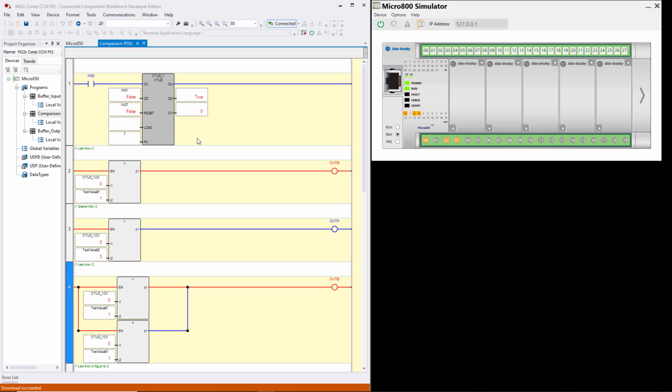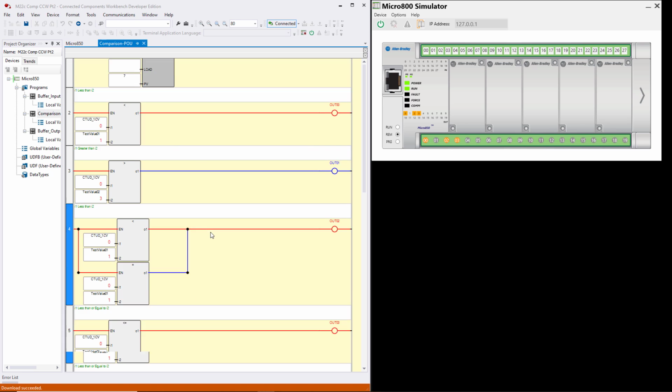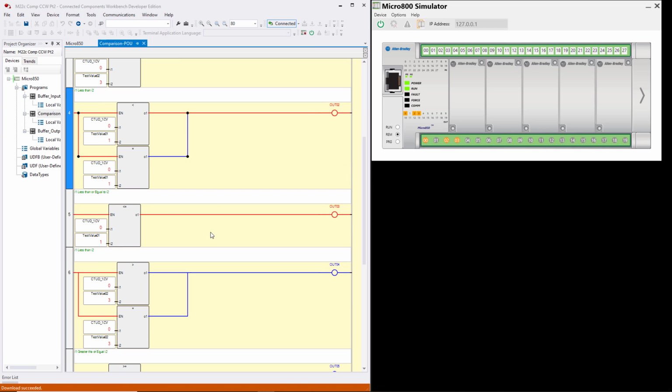Now if you're using a digital field device simulator, you probably only have 6 inputs and 6 outputs that you have wired up to switches and lights. In that case, instead of using IN27, I would just probably create a Boolean variable called reset and put it in there, and then just go toggle it from your mouse. Toggle it on, toggle it back off. Okay, we're back down to 0 now, so let's drop down here to something else.